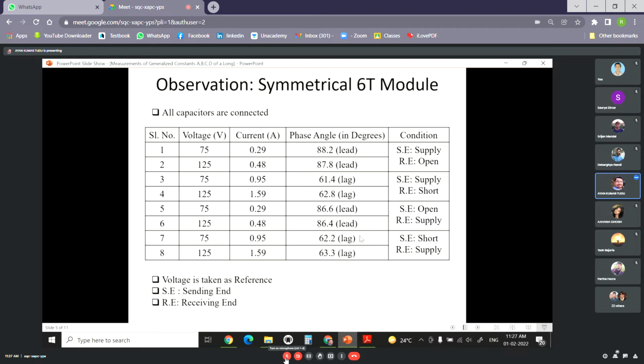That is, the reactive power generation should be exactly equal to the reactive power consumed or absorbed. Any mismatch of this reactive power balance will affect the bus voltage magnitude without affecting the system frequency.